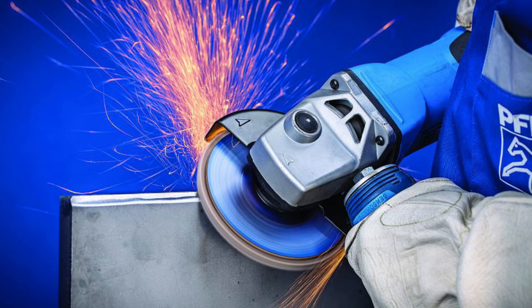Firstly, we need to cut all 8 pieces of the legs to size with a grinder. Then use a flapper disc to clean off all the sharp edges and then make sure all of them are symmetrical and proportionally correct. The next step is to weld the pieces together with a stick welder. It is important to keep all of them level with each other. When all the legs are connected to one another, the base plate that connects to the wood of the seat to the legs should be welded on.